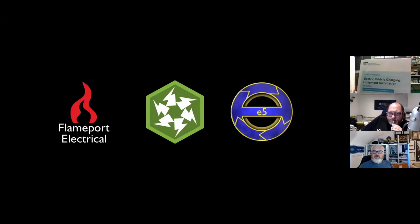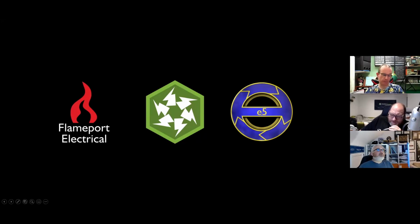That one, basically, the 60 amps thing is mentioned. But if you think about it, if you're putting in a 7 kilowatt charger, which is about 30 amps, the fact that you've only got 30 amps in total for everything else already in the property is not a lot. So you only need like one electric shower, and there you go. You're over the 60.